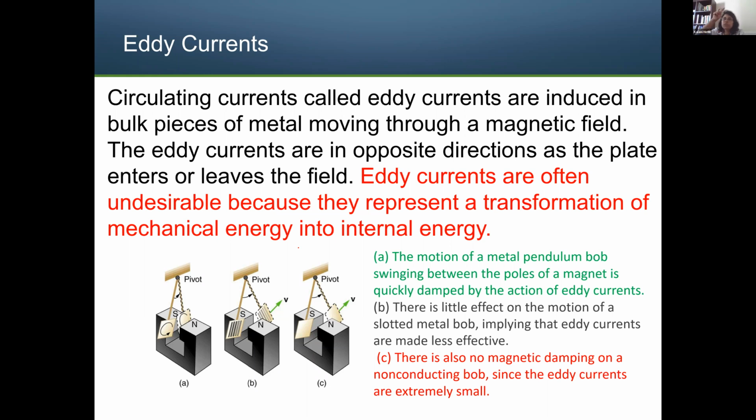If you have the tubes, if you drop the magnet using 3 tubes, if you drop the magnet in the copper tube, because copper is a conductor, as the magnet goes through, it will actually slow down the motion of the magnet. Other plastic and those things do not have the magnetism, so it just goes as a free fall. But in copper or the metal, if you drop the magnet, that will slow down the motion of the magnet, because it will create an eddy current on the surface of the metal, right?